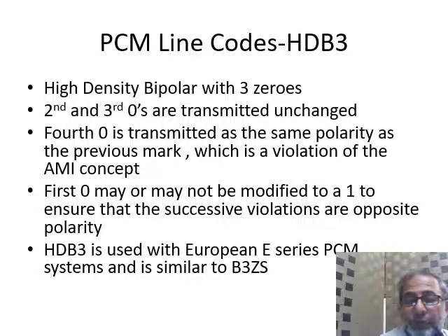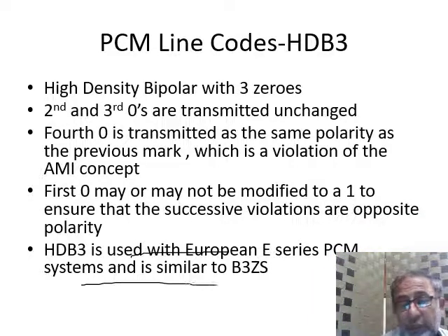So we basically do a violation of the alternate mark inversion concept. The first zero may or may not be modified to a 1 to ensure that the successive violations are of opposite polarity. HDB3 is used with European E-series PCM systems and is similar to, we can also call it, B3ZS.